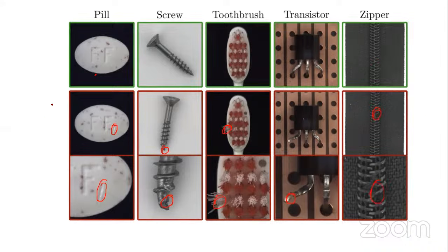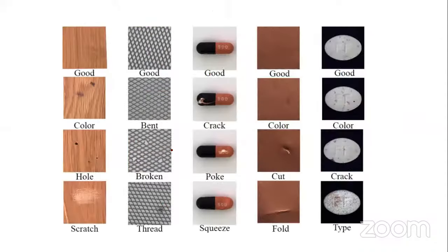We can see this with the naked eye, so we easily identify it. But a manufacturing unit handles tons in a day, and they cannot check that manually. So they need an automated process where the nails go on a conveyor, and vision image processing techniques scan the image and check for the proper structure. If it is a proper structure, it is pushed onto one conveyor; if it is an improper structure, it is pushed onto a different conveyor. This is another example of defects, such as color, holes, or scratches. These are the different defects available, and this is available on the internet also.